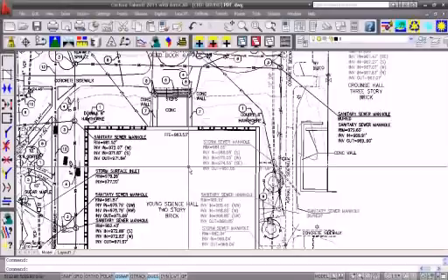So PDFs have become more standard because they also don't want to plot it out, or they make you plot it out on a piece of paper. So by getting a PDF, it saves you from having to plot it out on paper. It saves you from having to digitize, tracing in the line work, and it comes in not as accurate as the CAD file, but we'll see on this example, it'll save me a lot of time having to digitize and trace really tedious work digitizing contour lines.